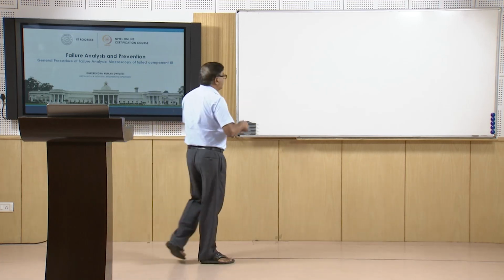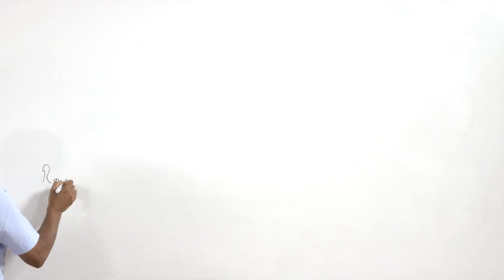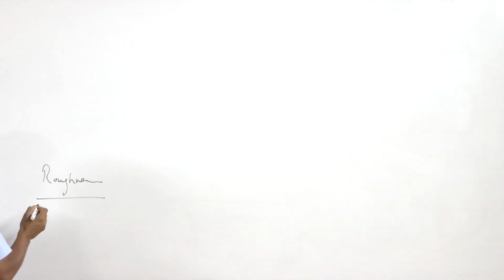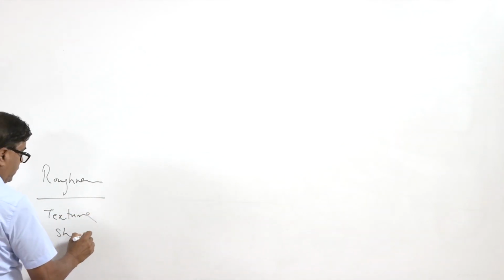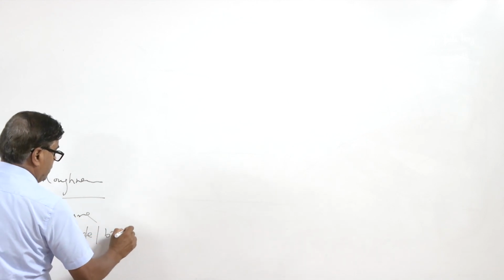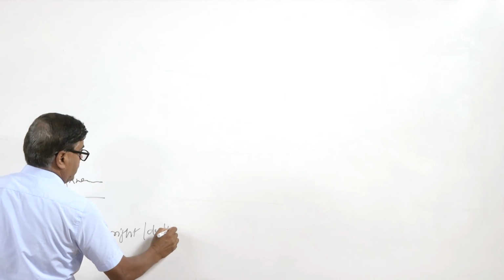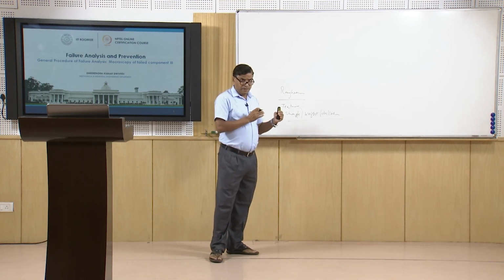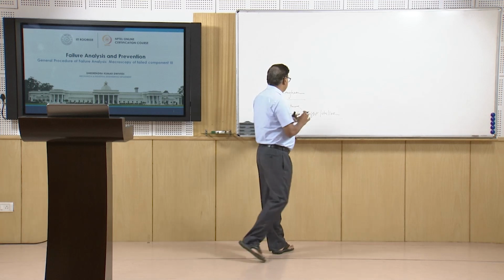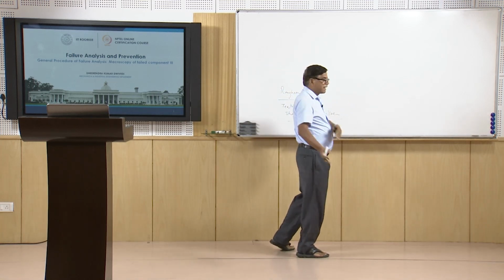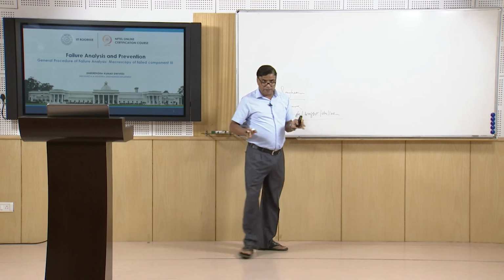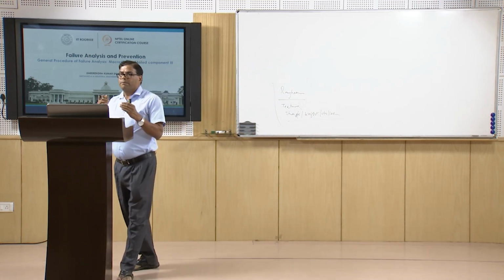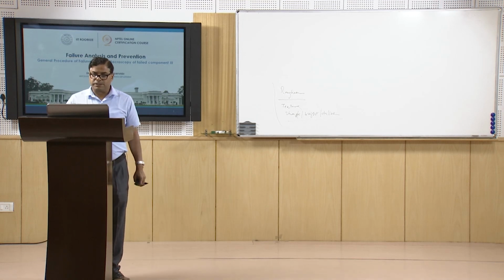We can gather a lot of information from the roughness variation present in the fracture surface, the kind of texture, or the kind of shade, the brightness or the dullness present on the fracture surface. So, the color, the roughness, the texture, or their variation will indicate what is going on and to what extent, and which type of mechanism was involved. All the idea about those things can be taken from such features present on the fracture surface.